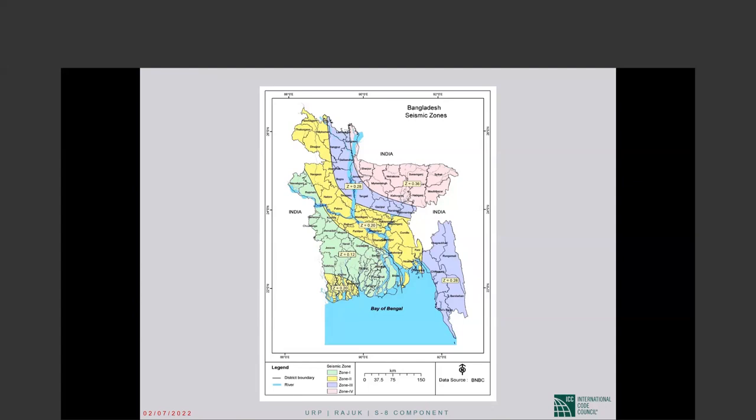Those who want to play it safe design a building that can withstand the design earthquake of the code with the infill intact. And they also design a building that can withstand the design earthquake with the infill all gone. Both ways, the structure should be able to withstand the earthquake. So the specific answer is the infill initially contributes to stiffness, but the contribution goes away when the infill is damaged in an earthquake.